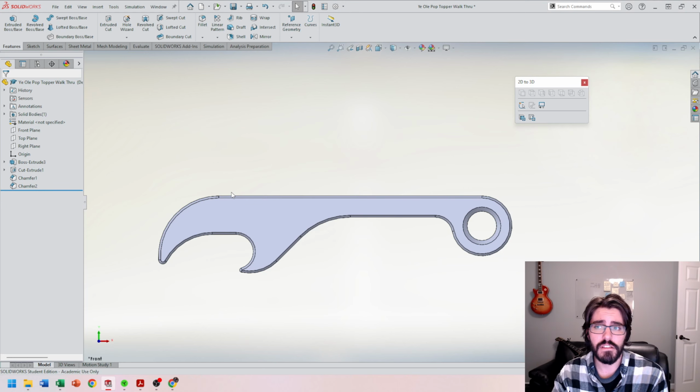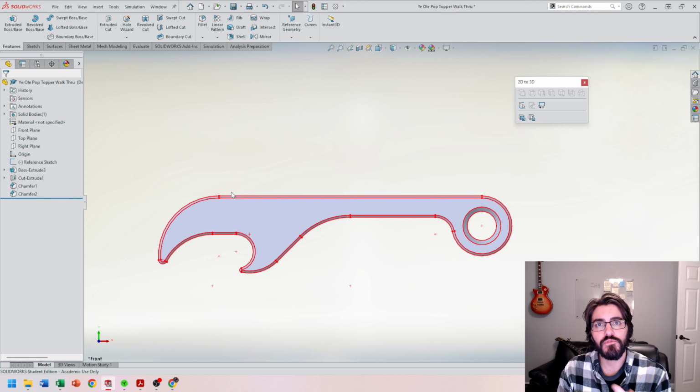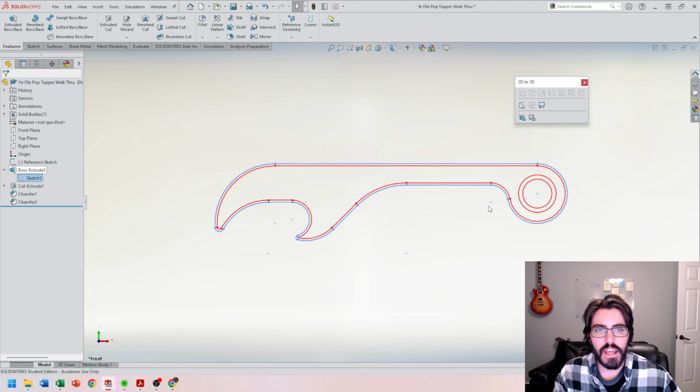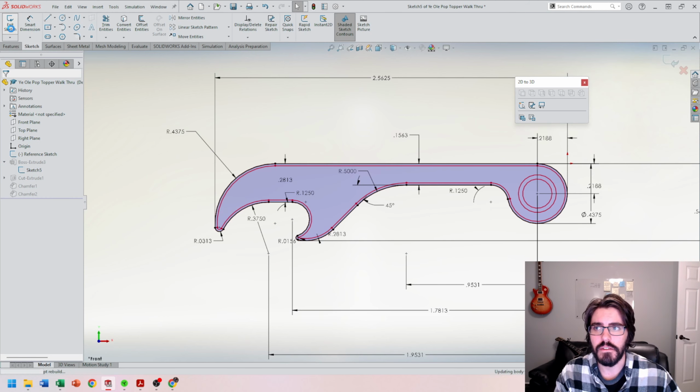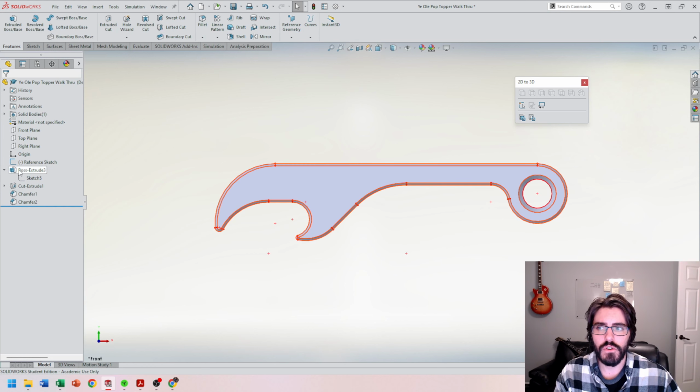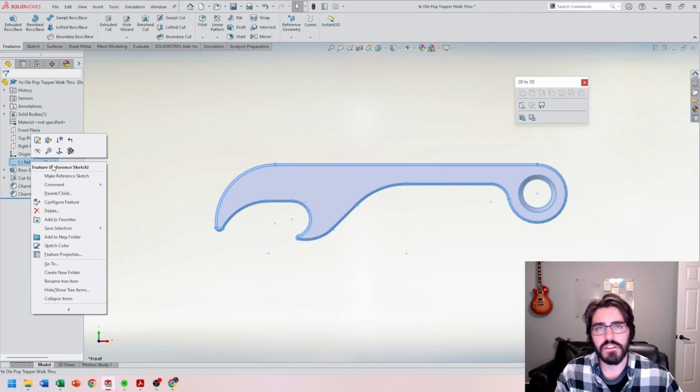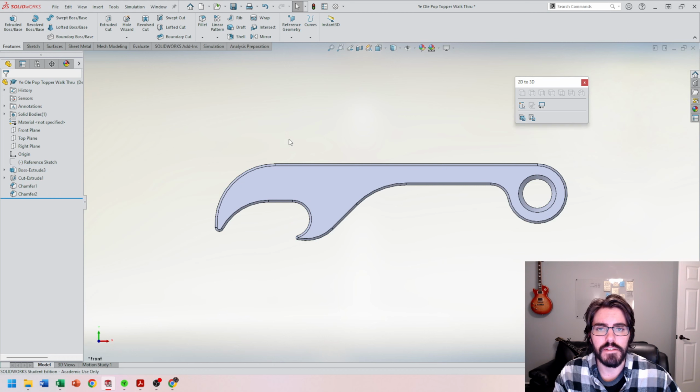We toggled back and forth by turning the sketch on and off, referencing it only to take measurements. We weren't actually creating geometry from the sketch that we imported. So it's fully editable now. I can go into the sketch and change the values as I need. So I'm actually just going to turn off my reference sketch. I don't need to delete it. I do want to keep it there just because it's good practice to have it in the background, so I'm just going to hide it.